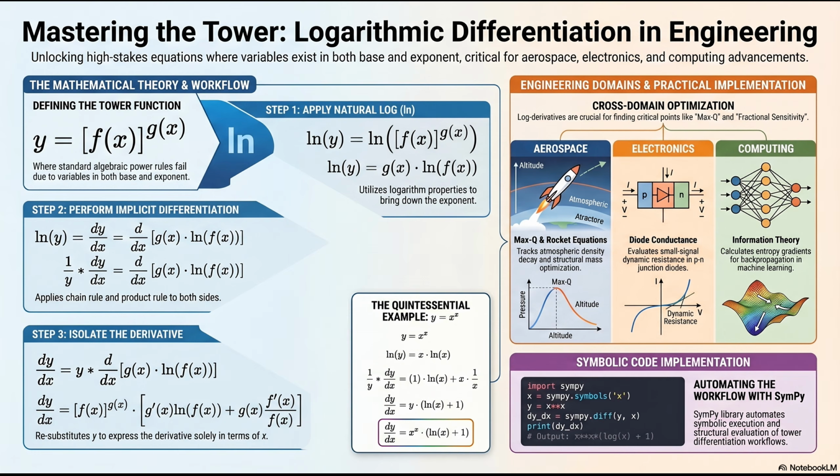Precisely. Now think about the physics of the rocket launching through that specific air. We have a vehicle entering an exponential atmosphere at supersonic speeds. Right. Its altitude is changing rapidly, and its velocity is increasing rapidly. They are coupled, time-dependent functions. The engineers need to track the exact derivative of the structural drag, which comes from dynamic pressure. And the notes say dynamic pressure is a combination of the air density hitting the rocket and the square of the rocket's velocity. Right. This is where it gets incredibly tense.